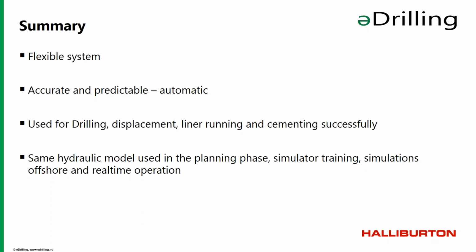What we've done for the cementing operations we've performed is that we go into a close dialogue with the cement provider, and then we do simulations both on our simulating tool and on theirs to try and find the optimum cement weight and cement rheology, and also the spacer that's going to be used to ensure that we achieve what we want to achieve, and that the cementing job is done without losses and successfully.